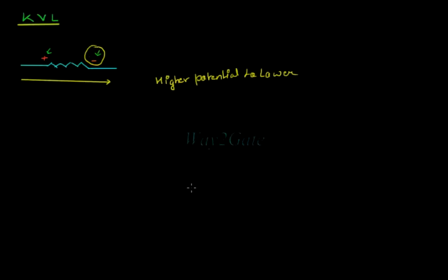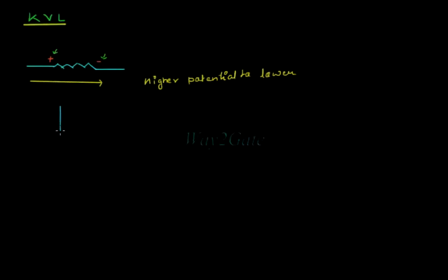Next, look at the polarity of the voltage source. While applying KVL in the circuit, if the direction of current is considered in such a way that it is moving from negative to positive terminal, then there is voltage rise across the voltage source. Therefore, voltage is positive.